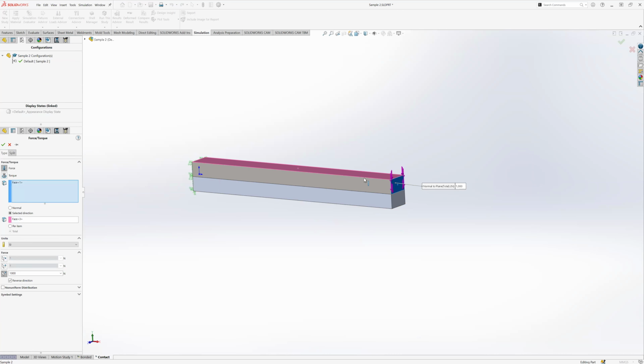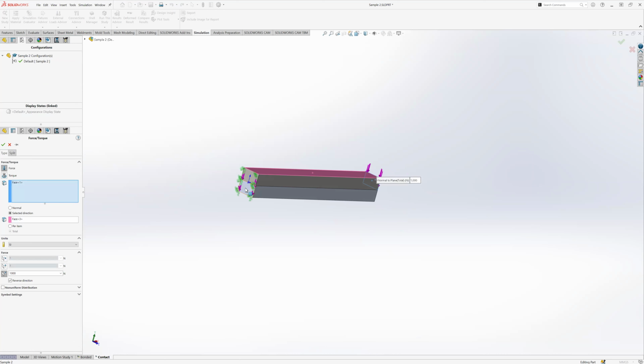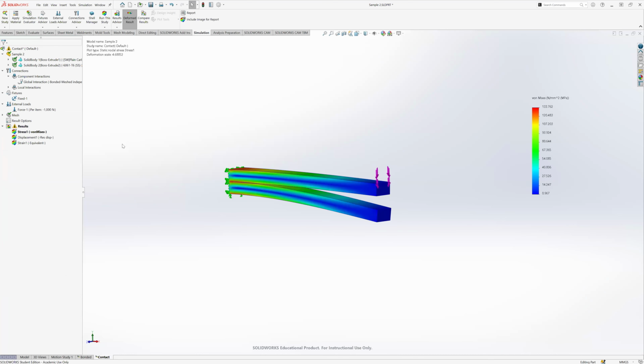So I don't want this right here. The reason for this is, looking at how this problem is set up, this top bar is pushing through the bottom bar. They're both still fixed on the side. If I took this fixture out, I would have an issue because this would just fly out into space somewhere. They still have to be fixed or have some sort of fixture. But now this one is pushing through here. In the last one I did, technically there's a contact, but the two bars really are not contacting each other. This one is deflecting more than that one. So we're going to change that around a little bit, and we'll hit accept here.